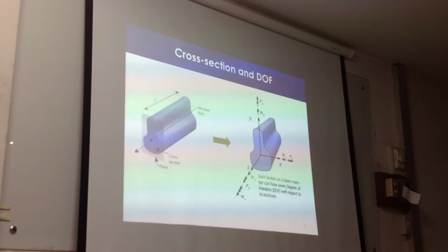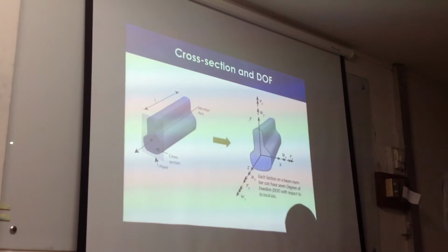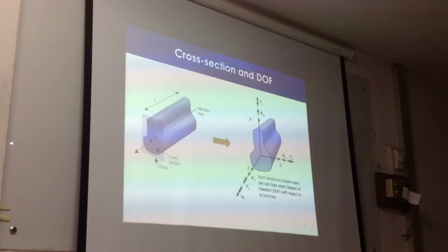Those cases are cold form steel. You know what a cold form steel is, right? Okay. Cold form steel is when you take a steel plate and you bend it into a section, it's not solid. The entire design of the cold form steel is dependent on warping. In certain cases, when the ends are fixed, warping becomes important. When warping is restrained, then warping becomes important. So it's complicated stuff.